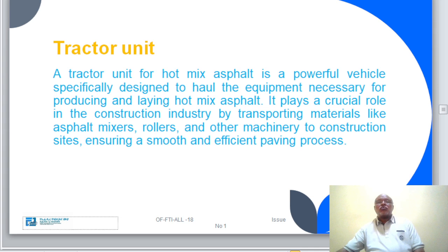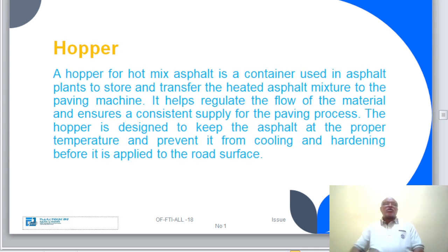Let's see the first one, which is the hopper. The hopper is the area where the hot asphalt is discharged from the trucks or lorries. The sides of the hopper, or wings, can fold hydraulically towards the center to ensure that all the material is pushed onto the conveyor. The capacity of the hopper depends on the model of the paver, and in most models its capacity varies from 5.5 to 6.5 cubic meters, which in terms of mass is approximately 10 to 13 tons.